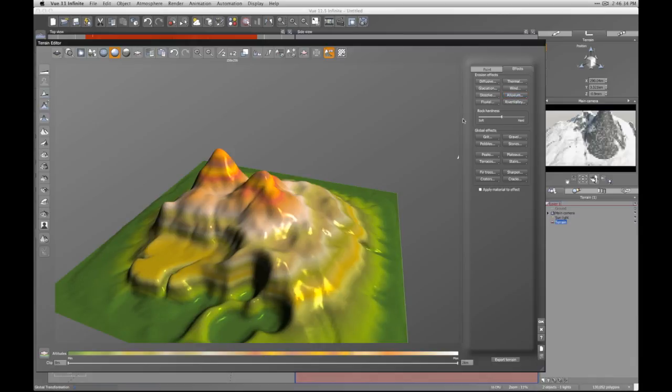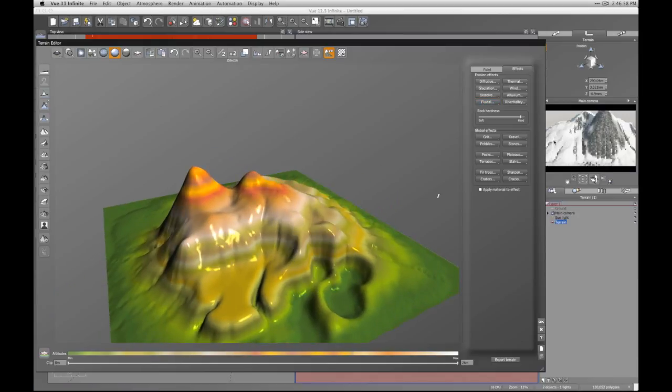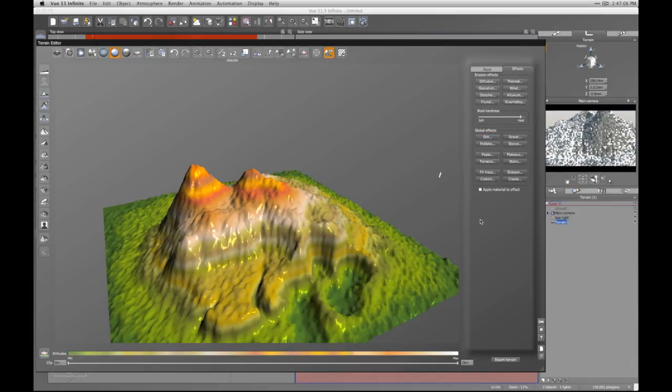Pretty cool. If you want more of an effect, you go soft, and we'll get much softer erosion, as if it was sand that was eroding. When it's set to hard, you'll notice that you get really sharp cracks forming in it, especially with the fluvial, we'll get very thin, sharp cracks. You can see these forming now. And we can also add a bit of grit. You can see that's had a huge effect over here. We can also go undo.